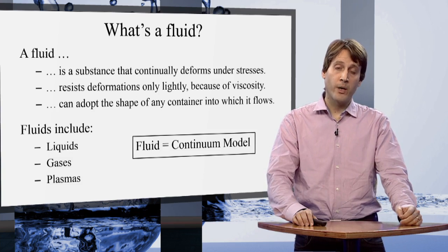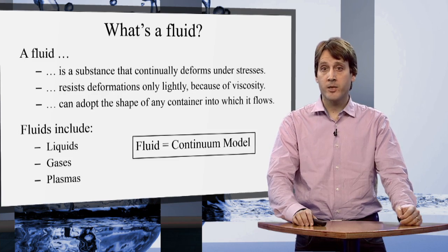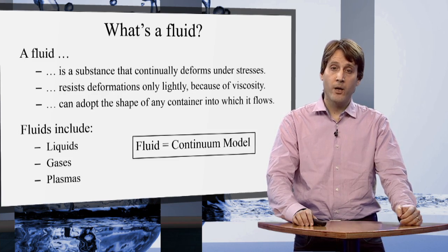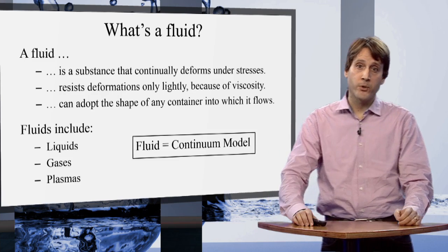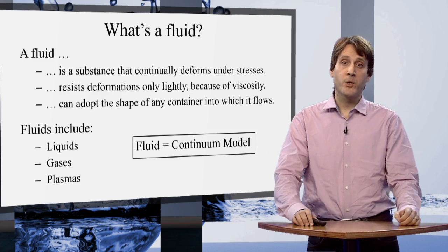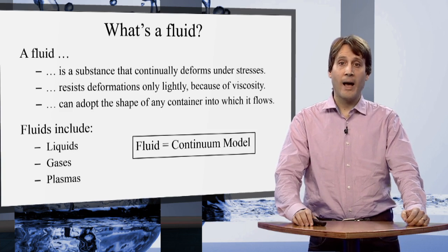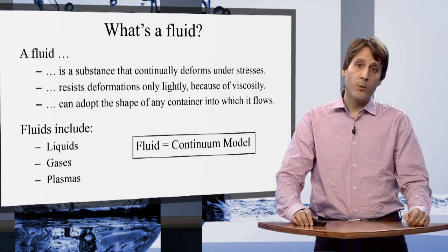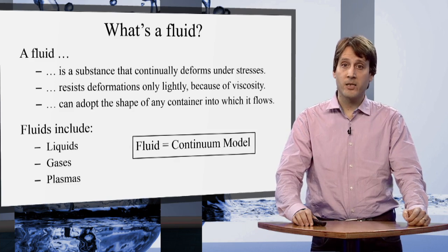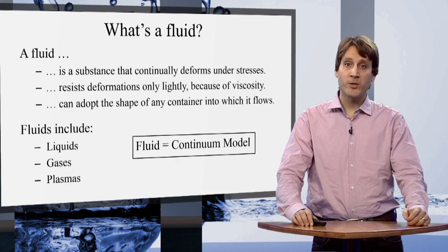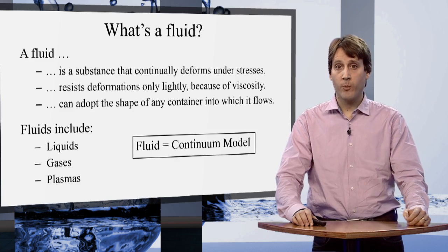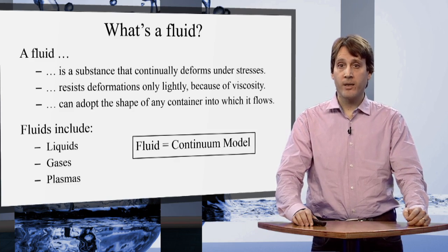We have learned before with cellular automata that it is possible, and it makes sense, to model continuum matter with a mesoscopic approach, with particles which are somewhere between the molecular nature of the actual matter and the continuum approach. Today, however, we will extend lattice gas automata and move from the mesoscopic approach to a continuum approach to gain numerical efficiency.